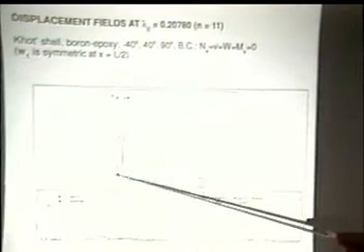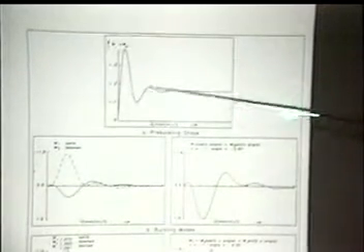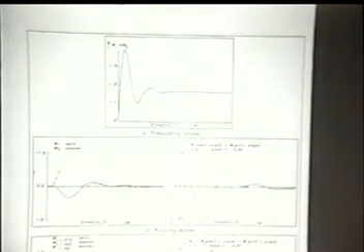We are using nonlinear pre-buckling, so you see here the Poisson's effect, and here you see the edge effect. This was a shell that was 12.5 inches long and radius 6 inches. So L over R was 2, rather long. And so in most of the shell you have the membrane solution valid, and only at the edges, the edge effect.